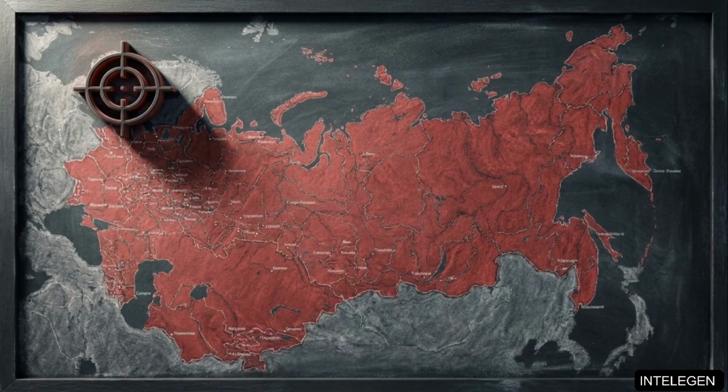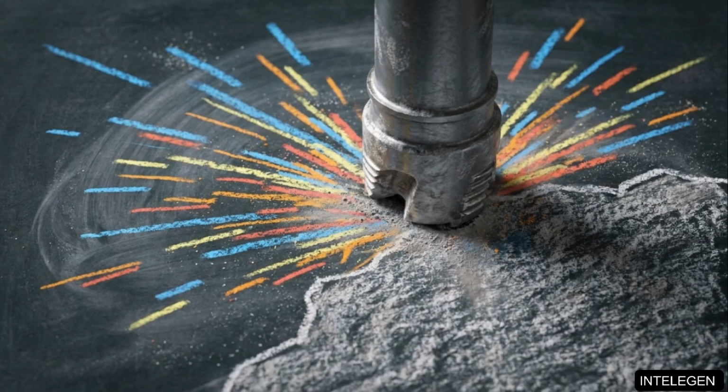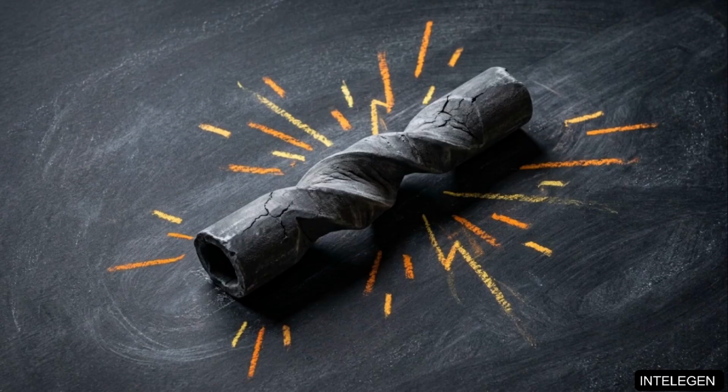In 1970, the Soviet Union adopted a brute force onshore strategy. Located in the frozen Baltic Shield, the Kola Superdeep Borehole, designated SG3, was an attempt to penetrate 15 kilometers deep into ancient, stable continental crust. The mechanical friction of this approach was immense. Standard rotary drilling, where a surface mechanism turns the entire drill string, becomes impossible at extreme depths. The torsional friction and mass of several kilometers of steel pipe would simply overwhelm the rig.